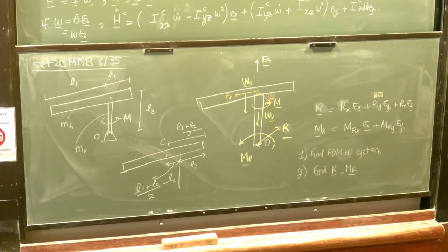Yeah, I think this is the section. When I'm trying to find IZZ, I'd have to use the parallel axis theorem. So I'd say the moment of inertia through the center of mass, then offset it by the distance d, which we found earlier. You don't use the z component of the distance though, it's just the x and y components, right? Yeah, just the x and y components.